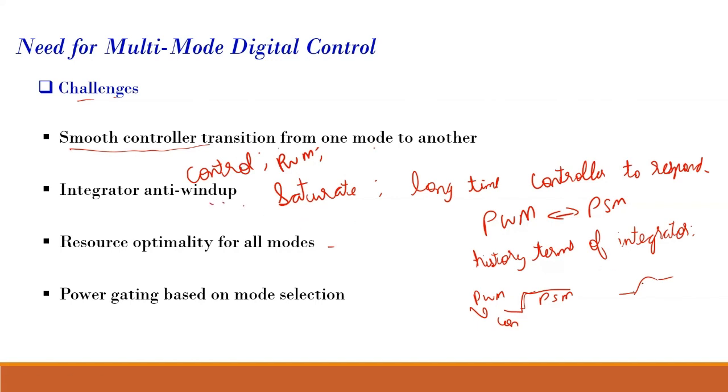In certain cases, in case the integrator gets saturated, we have to have an anti-wind up arrangement. Normally also we will keep certain saturation limits, so that we don't want the duty ratio to exceed certain limits. We have certain protection already written in our code.